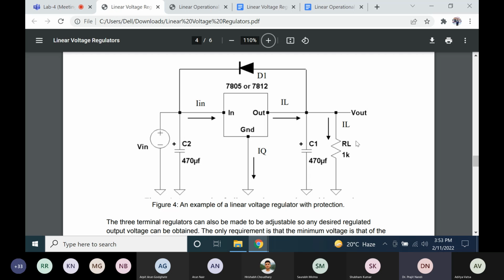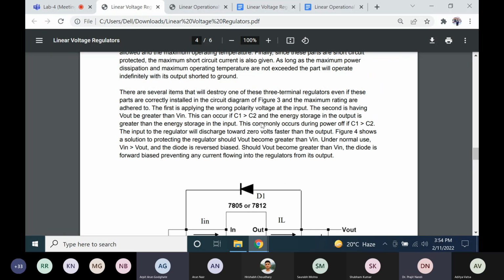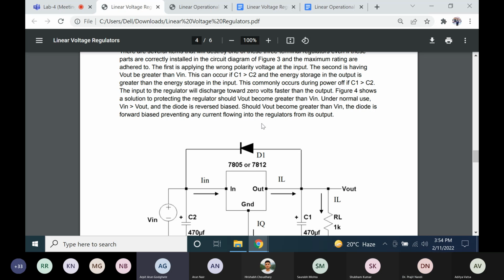But for now, some simplistic explanation can be, for example, in cars, right? If you are designing an electronic system in cars, depending on the motor that you have. So let's say you are starting your car in the morning when the engine is cold, right? Or let's say there can be failure incidents in a car. So during these kind of events when the motor is behaving in a knee jerk way, there can be charge dumped onto these electronic circuits from systems external to the IC itself. So because of charges getting dumped on the output node, there will be scenarios where V out can become higher than V in.